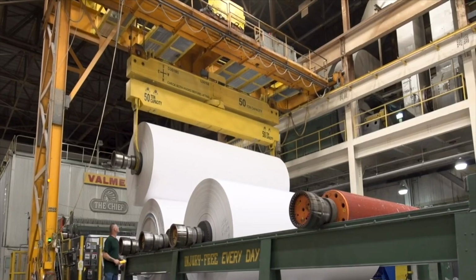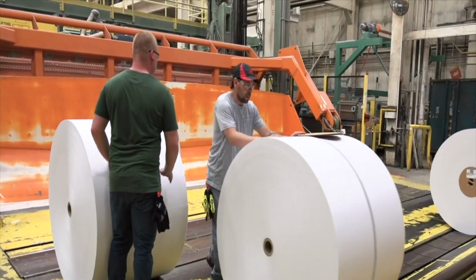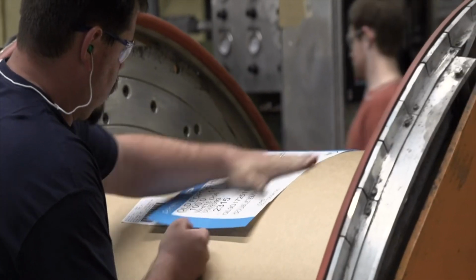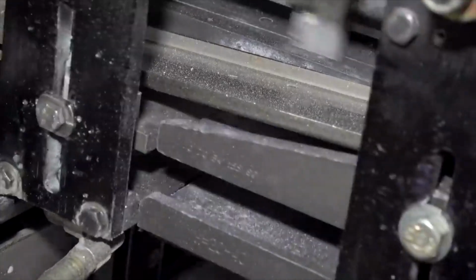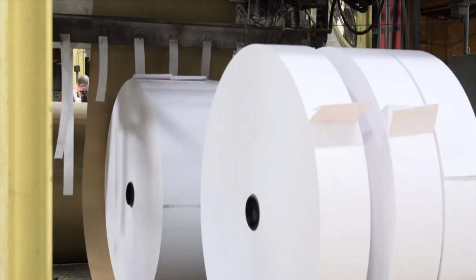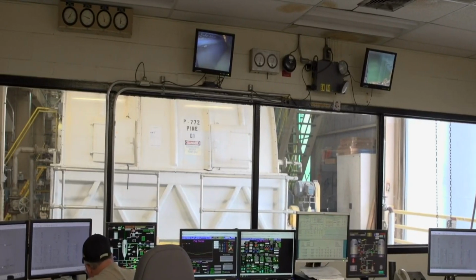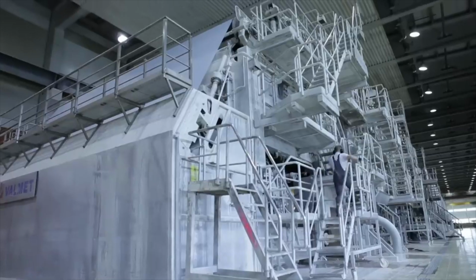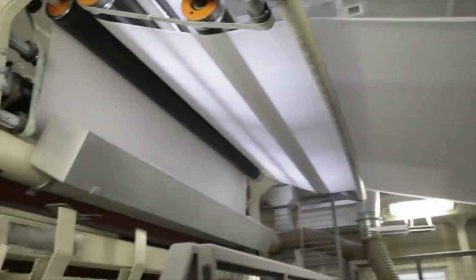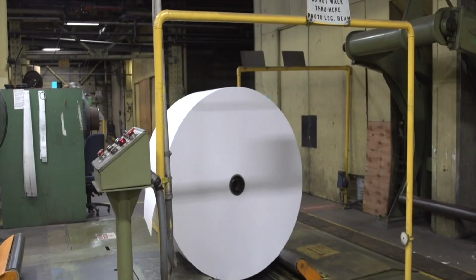After the paper has been formed, pressed, dried, and possibly treated in additional stages, the final steps are cutting the dried paper rolls into usable sizes and packaging them for transport. Special cutters slice, trim, split, and rewind the paper into different widths and diameters, depending on what it will be used for. Trimmers make precise cuts needed for applications like copy paper, while rewinders rewrap large rolls for industrial uses. The cutting and finishing stage also does final inspections for defects before packaging. Folded paper goods may undergo additional corrugating, creasing, and folding steps as well. The finishing work turns monster paper rolls into neat packages of all kinds: copier paper, notebooks, tissue boxes, and more, ready for shipping to distributors and end-use consumers.